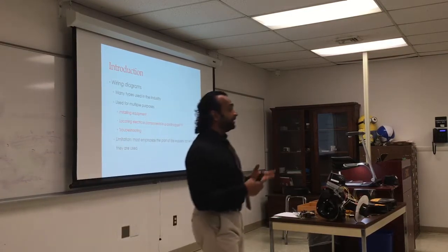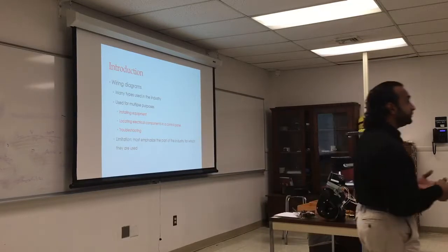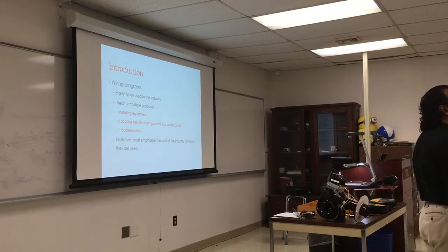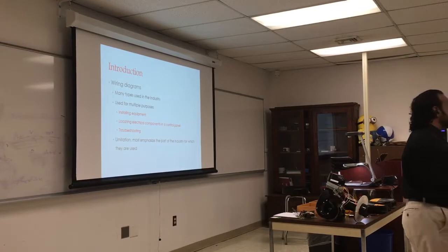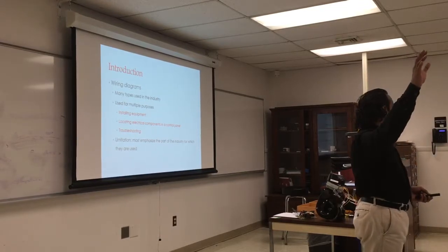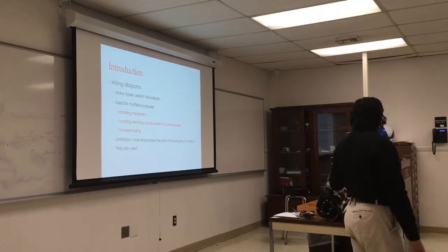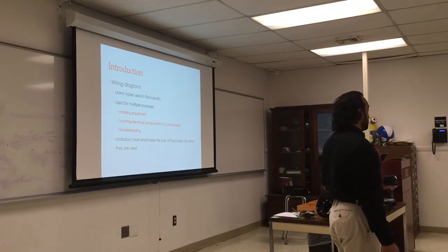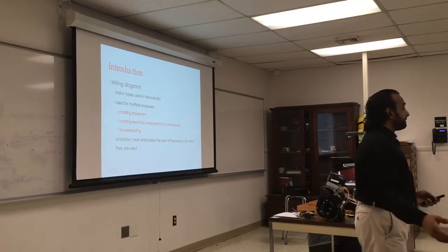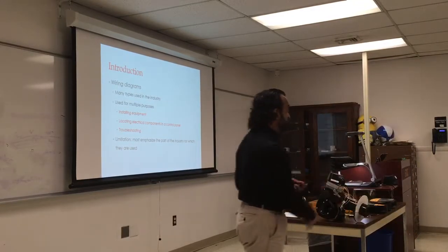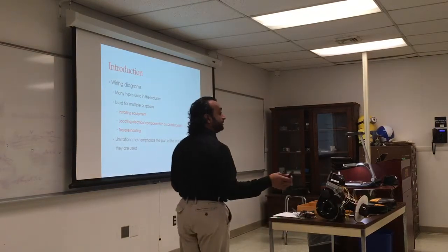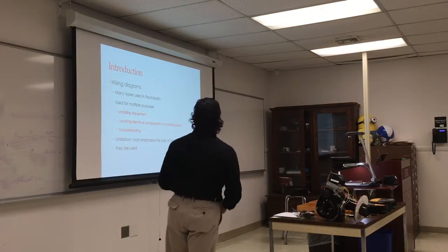And now in the lab environment, it's very easy because everything is in front of you. All the equipment are close. When you go to a house or an actual building, you'll see the equipment all over the place. Thermostat will be in the third floor, second floor, and the oil burner will be in the basement. And the power coming from probably far away. So you have to be able to trace those power and see where it is coming from.